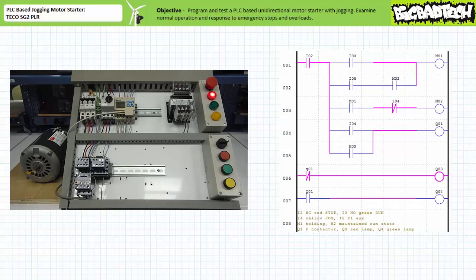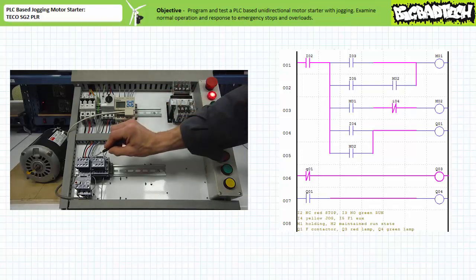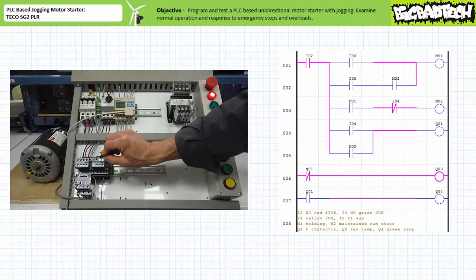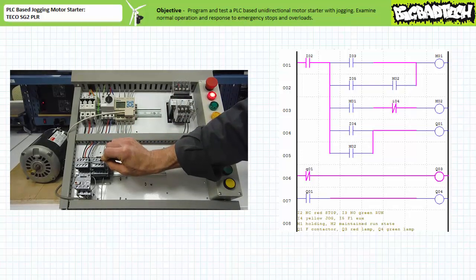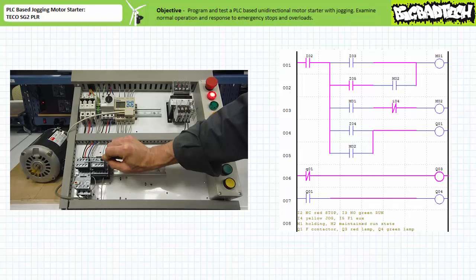When a technician physically pushes the F contactor closed using an insulated tool, the F contactor physically makes connection and the motor starts as can be expected. The make instruction examining input I5, the now manually closed F1 auxiliary contact, does allow logical continuity in rung 2. However, the make instruction examining M2, also in rung 2, does not allow logical continuity and the holding circuit is not established. Despite the F contactor being held closed, the F contactor coil is not energized and only the technician's purposeful act of holding the contactor closed allows the motor to operate.